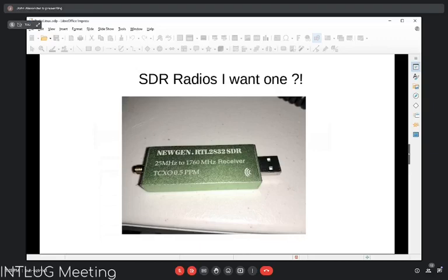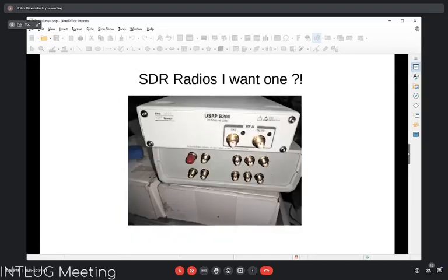But it has a more accurate crystal in there, a TCXO, so it's temperature compensated. That box gets quite warm, nice and toasty, and as it gets hot, things start to drift. But in this case, somewhat less so. So it's a good investment. If I was going to do that, I'd certainly, well, I have done. If you're going to use it for anything, it's worth having this version.